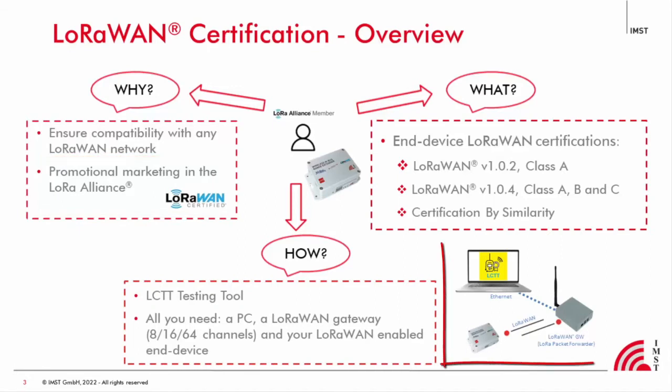Everything you need to run the LCTT tool is a PC, a LoRaWAN gateway, and your end device. If you have finished the design of your product and you are interested in getting it through the LoRaWAN certification, the LCTT tool may be an interesting option for you. This tool has been developed by the LoRa Alliance to allow an easier pre-testing of the devices before sending them for the formal LoRaWAN certification.